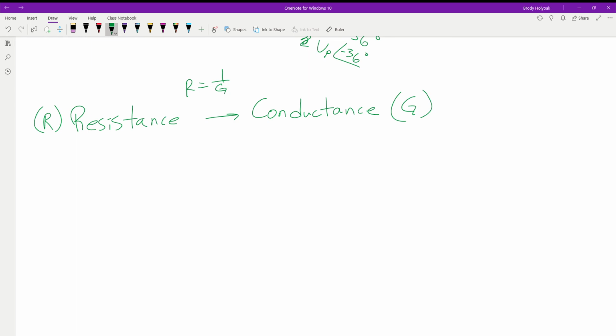So like when we were finding parallel circuits, we would take the reciprocal of the resistance, add the conductance values together, and then take that total value and convert it back into a resistance. We do the same thing, we just have a separate name for them for reactive components. So we have reactance, that is an X. The reciprocal of that is susceptance. It's the susceptibility. It's how easily is the device able to charge or discharge or build up a magnetic field. How susceptible is it?